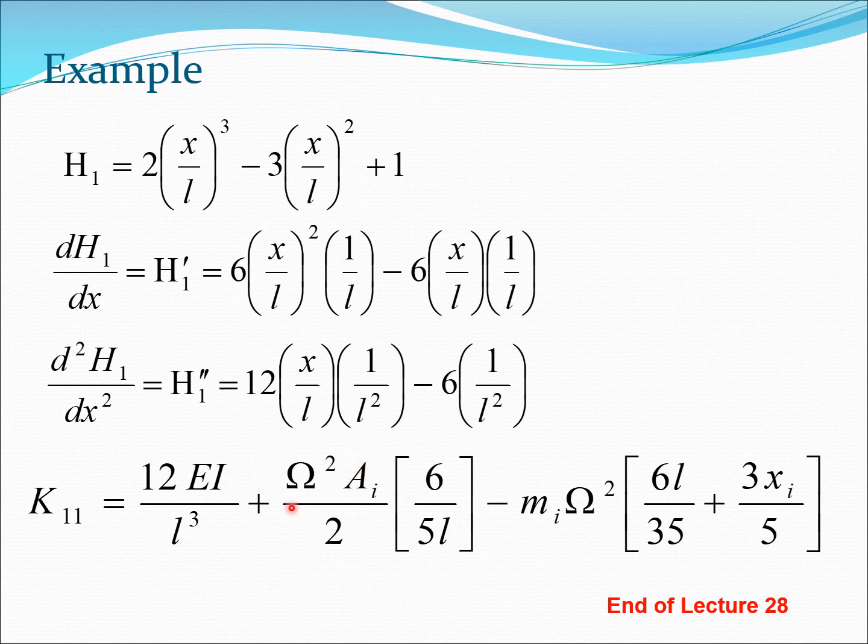This is relative to rotation speed, and this is essentially all the part of the blade which is to the right of where you are at element i, and then you subtract this slight portion which is actually from xi to x, and that is this particular part of the centrifugal force. So this is the stiffness matrix for the rotating beam.